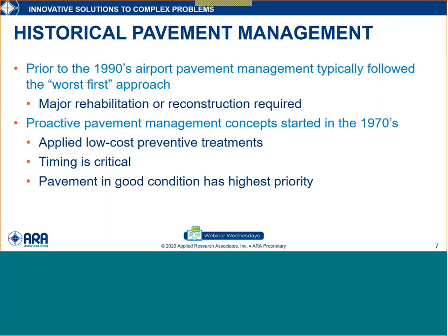But today we're firmly in that proactive category of pavement management, where we're looking to apply low-cost preventative treatments while the pavement's still in good condition. In order for this approach to be successful, timing is critical. And if we're doing things correctly, we're going to assign a higher priority to fix pavements that are still in good condition as opposed to those pavements that have deteriorated into poor condition.